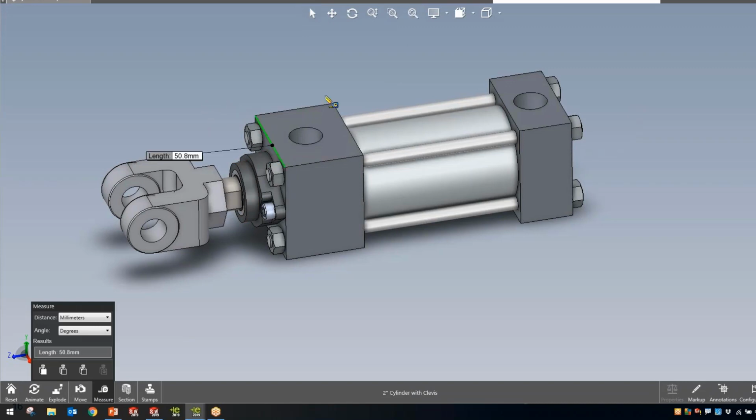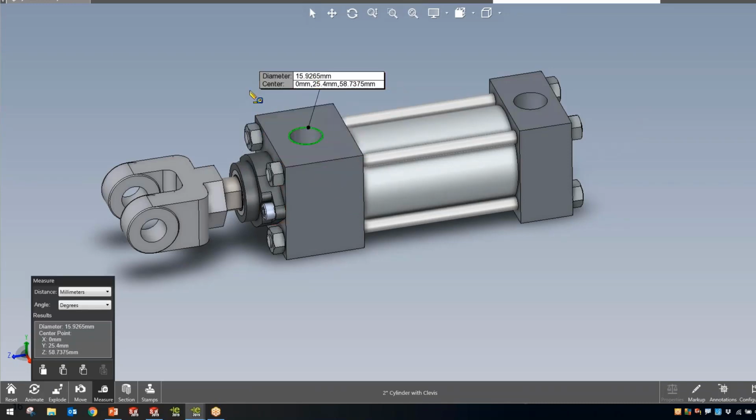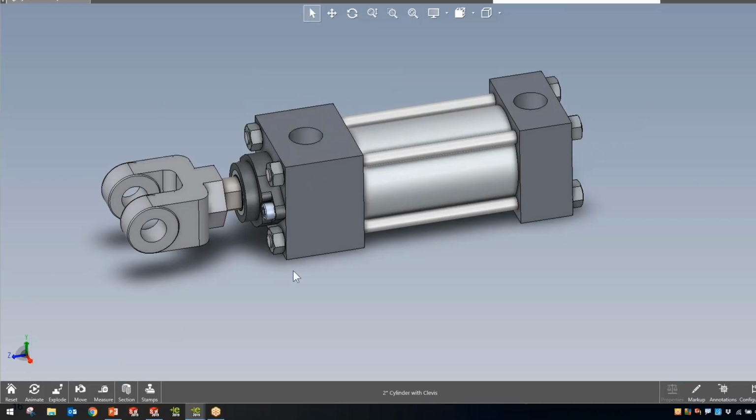the measure tool. Previously, prior to 2018, in order to be able to measure distances in an eDrawings file, you had to have eDrawings Professional and also a file that was unlocked for measurement, of course. Now with 2019, all of the features related to eDrawings Professional 2018 and earlier have been migrated into the standard free eDrawings that can be downloaded online. So now one of the things included in that, most importantly, is the measure tool can be used in the free version of eDrawings. So you can lock that down, of course, when you're saving the files out. But now somebody with the free version of eDrawings, you can send them files and they can take measurements to make sure that everything's matching up as they want their design to look.